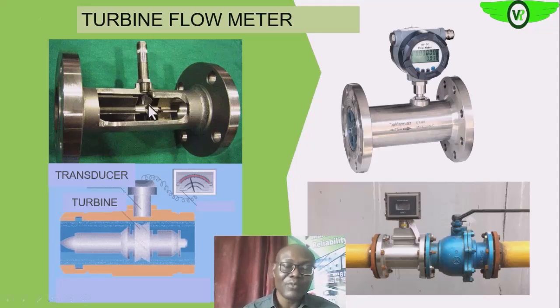So in the turbine flow meter, we have a turbine in it that turns when it is impinged upon. That is, when the fluid flowing through the pipe strikes it, it turns it. So the volumetric flow rate increases, that is, the number of pulses, like we said earlier, increases with the flow rate across this section of the pipeline. So this way, at the end of the day, it gives us the volumetric flow rate.